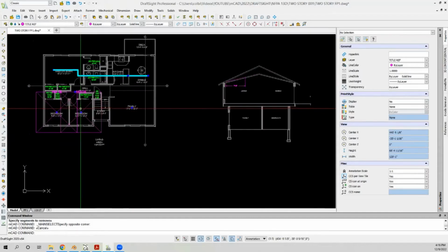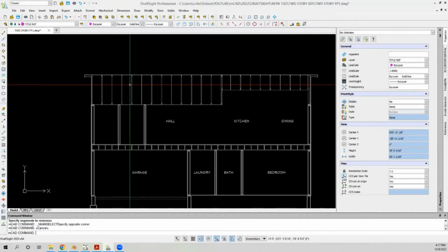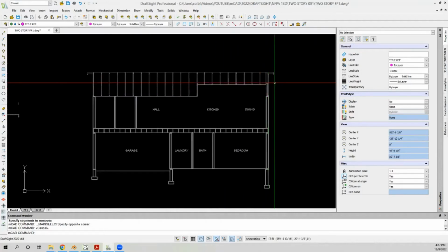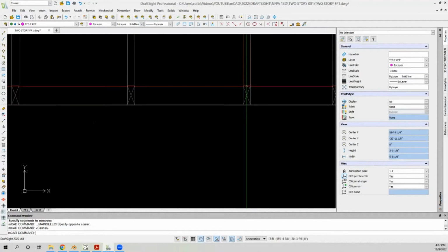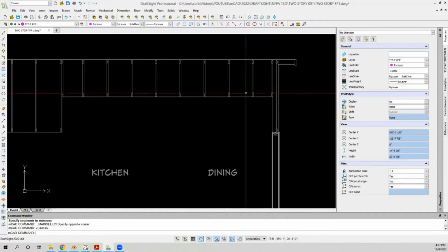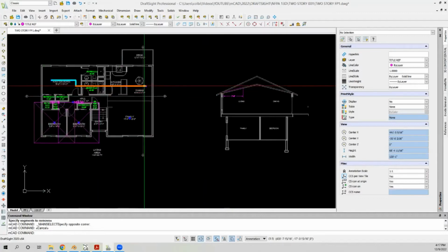And I'm laying this out. Here's my section here. There's a truss. So I got on 2-foot on centers, there's scissor trusses in this area and then regular trusses over here. This section is right here, and you can see they're laid out on 24-inch centers. And so I want to run this way through here so that I can just lay my pipe on top of the bottom chord. This is the bottom chord of the truss. I just want to lay my pipe on top of there and strap it right to the top of there with my hangers. So that's what we're doing here.